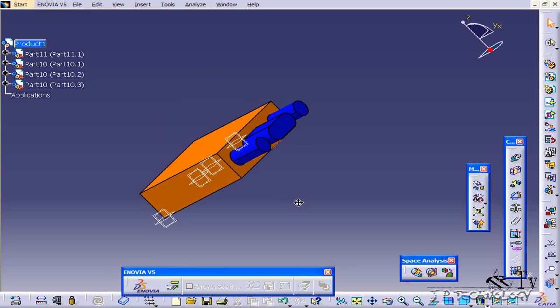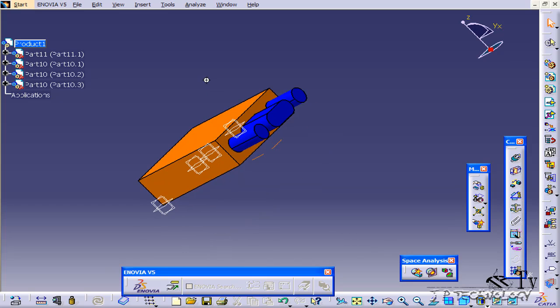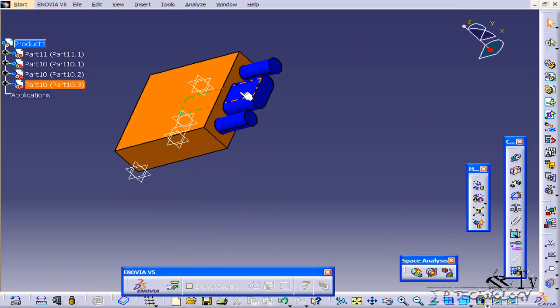So using the snapping tool, it's really easy as it kind of combines the coincident and contact constraint. For positioning, it's my favorite one. I'm able just to throw everything in, snap everything together, and it looks really good. Now the only problem, like I showed you, is that with some components you're going to have to insert them differently than you would using the constraints. So it's just a little bit of problem solving when you're putting them in.